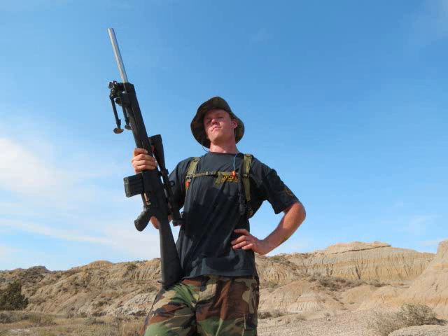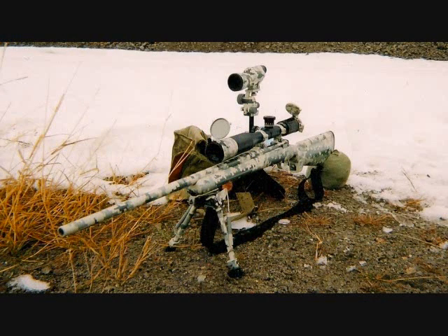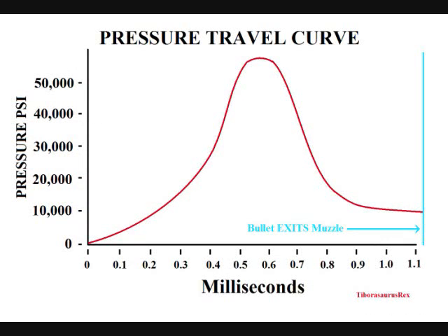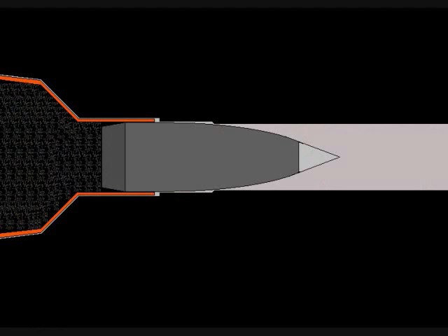But a cold bore offers more resistance to projectile movement and is less susceptible to coppering, even at higher velocities. So in general, cold rifle bores and warm rifle bores are going to have different resistances to the projectile movement. A lot of that has to do with the engraving resistance pressure. When we're talking about that bullet getting into the rifling, right as it goes through that forcing cone, it's actually going to take up about 2% of the total propellant energy just to overcome that engraving resistance. So it's a significant amount of the power that's expended in there going just to engrave it. And it's going to be easier or tougher to engrave that bullet based on the temperature of both the projectile and the bore.